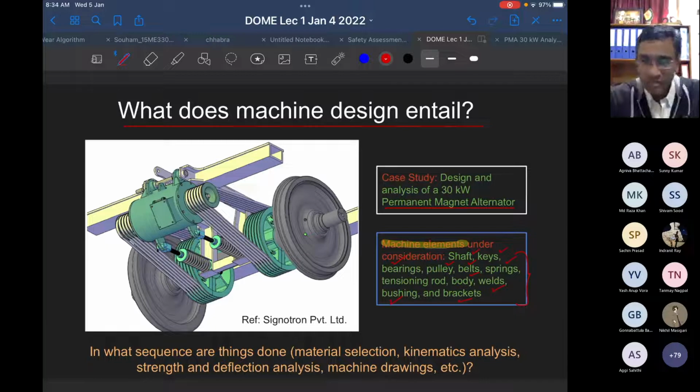A comfortable level of force that you can exert would be somewhere around 15 kg. So using a 15 kg force, you need, let us say, to lift about 1 ton force. So you need the system to provide you some mechanical advantage.